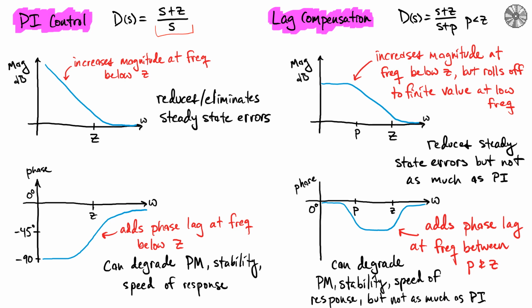And so what ends up happening in the magnitude plot, the magnitude plot for 1 over s looks like a slope just directly downwards, like this. And the zero, as we saw before, looks close to 0, and then it breaks as it goes up. And so these two cancel out. This branch up here going up and this branch going down cancel out and provide us with this relatively flat region here. And then this relatively flat region and this slope here creates this slope that you see in the blue. And so that combination leads to this type of magnitude plot.